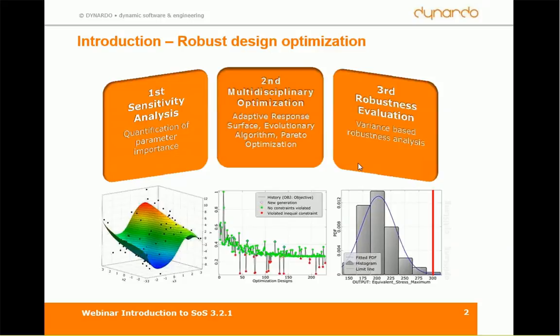Building a so-called meta model afterwards helps one to identify important parameters, which means parameters it is worthwhile to take into account in further analysis steps like a multidisciplinary optimization, defining some sort of criteria, for example, minimizing the error norm between the reference and the design signal. Already at the optimum, one might now define uncertainties on the input side, validating the robustness of a product with some variance-based criteria. I would like to show you in this introduction that random fields might help one essentially in each of these described steps.